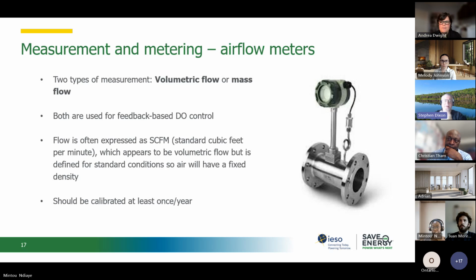Andrea, I'm just going to reinforce what you said about the current sensors. You're right, they're not a revenue grade meter, but with proper setup, they can be almost as good at a small fraction of the cost. So don't get caught up sometimes in the need to go after revenue grade meters for sub-meters for doing this kind of monitoring.